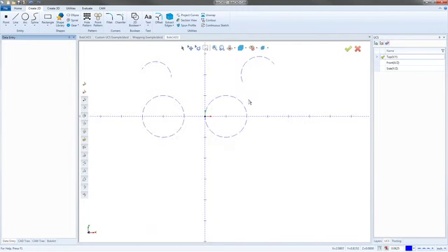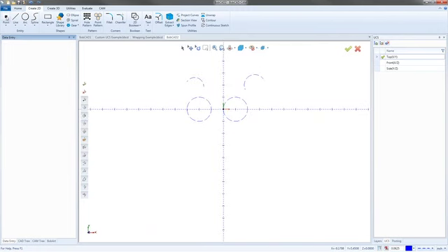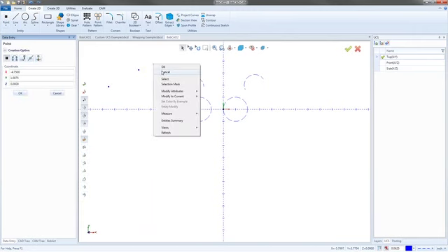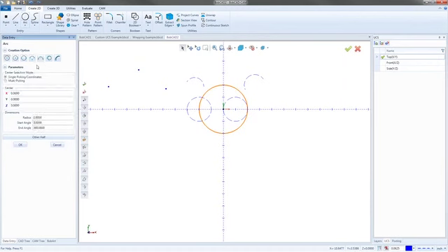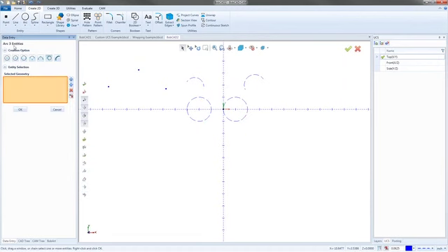And then the next one is the normal 3-point entity. I like to use points for this one, so I'm just going to go 1 there, 1 there, 1 there. If you got 3 known locations and all you're trying to do is put a point through all 3 of them, you just go arc 3 entities. We go 1, number 2, number 3, and it'll create that arc, and then we hit OK, and there we have it. And then the last one is fit arc.